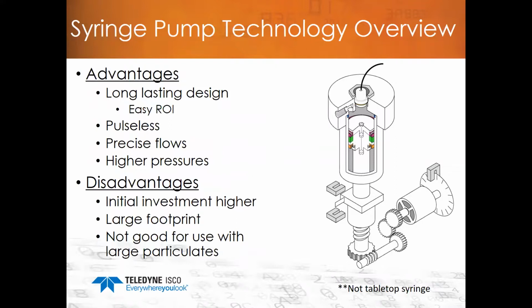Another key feature of syringe pumps is pulseless flow. Pulsation can be bad and can change the chemical characteristics of the material during the chemical reaction. It can also have an impact on the amount that's dosed out, etc. So when you're looking at something that has that sensitivity, you need to be sure you find a pump or a pumping technology that can handle the least amount of pulsation as possible. Syringe pump technology is as close as you will get to complete pulseless flow.